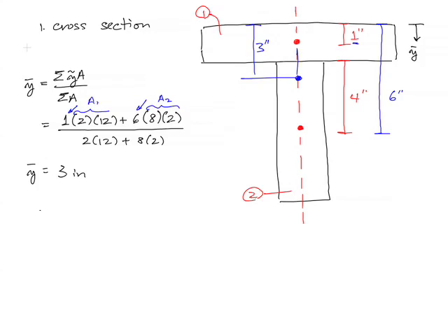Next thing we have to do is calculate the moment of inertia. And let's start with I_z. So we'll call this Z and this Y, consistent with what's on the front page. I'm going to write this all out, and I'll label it in just a minute. We're going to do I_z, and here we're going to consider piece number 1 and piece number 2 separately. We're going to do a bh cubed over 12 plus the parallel axis theorem part, as you'll see in a moment.